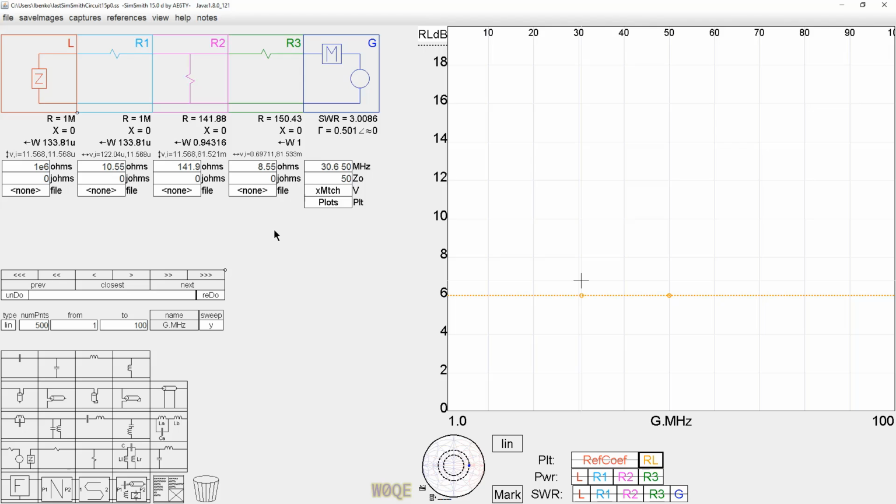We're doing that basically with an antenna analyzer. The device we're using to make the measurement is a single port device. We don't need a two-port network analyzer to see if our attenuator is good. A single device like an AIM 4170, 4300 has a single connector on it, can read this impedance, measure return loss, and give us the answer. Of course, a two-port network analyzer that has a generator here and a receiver over here can measure it directly.